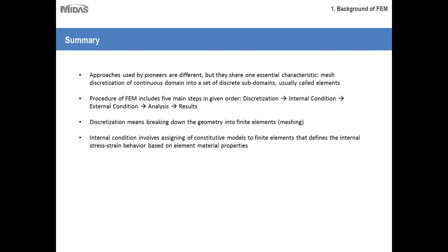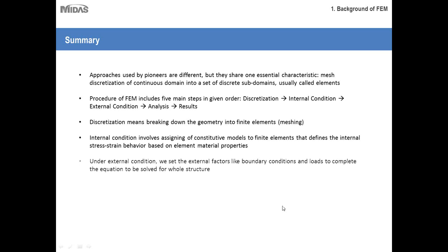Internal condition involves assigning of constitutive models to finite elements that defines the internal stress strain behavior based on element material properties. So how these stresses will propagate, how the deformation would occur under different types of loads, when the material will yield is something internal to the structure, and that could be controlled by constitutive models.